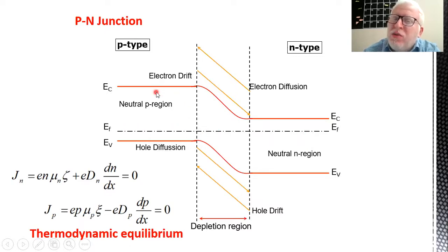Then you merge these two semiconductor parts based on this horizontally aligned Fermi level. Accordingly, the built-in potential or the barrier starts to appear, and all these things related to the p-n junction, which we have already investigated in a complete lecture, lecture number 2. Now, we are going to repeat the same process, but instead of having two semiconductor materials, we will have one semiconductor, maybe n-doped or p-doped, and we have a metal.